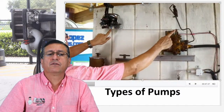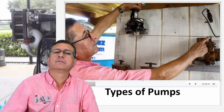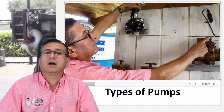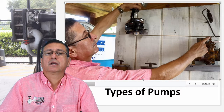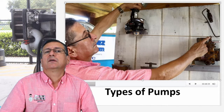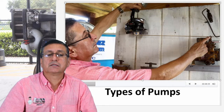And this is the handle for the RPMs. The handle of the RPMs is directly connected with the station, with the control at the pilot hand. In some cases the connection is mechanical, like this, with a cable, or in some cases the connection is electronic. We are going to talk about those controls in our class of auxiliary systems. Both of them have the same function: control the handle on the fuel injection pump. With this handle you administer the RPMs. You accelerate or decelerate. Yeah, that's the control.